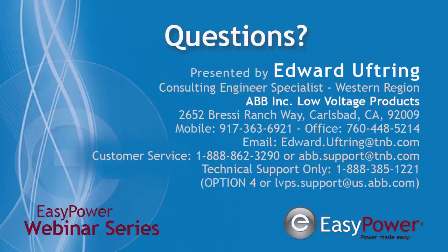2 milliseconds, how many cycles is that before the breaker opens? 2 milliseconds is a quarter of a cycle. So it's not even the half a cycle that UL requires. It is actually less than that. It's half of what UL requires.